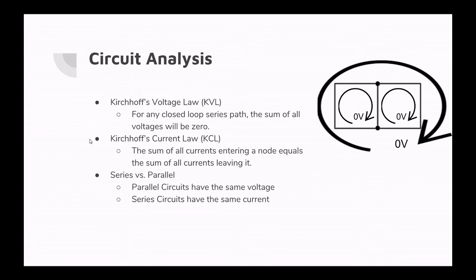Next up is Kirchhoff's current law, or KCL. This law is kind of the same coin as KVL, but said in a different way. KCL says that the sum of all currents entering a node is equal to the sum of all currents leaving it. And once again, if you look to the right, here's a mock-up. Imagine we have a blown-up section of this circuit down here, and we have current flowing into the node. Well, the current leaving that same node must sum to the same amount. I1 must equal I2 plus I3, assuming that I1 flows into the node and I3 and I2 both flow out.